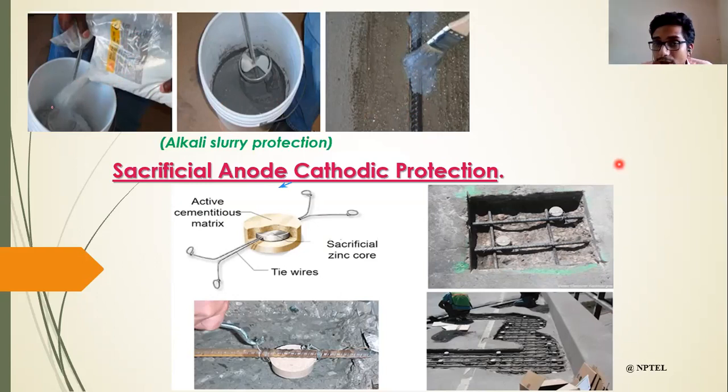The one thing we should ensure, if you paint something, is that there should be a proper bonding of the new concrete system that you are going to provide in that particular region. The bonding should be very good. As I told you in the first couple of slides, very early on, the bonding system matters a lot in the case of repair work with the substrate system.